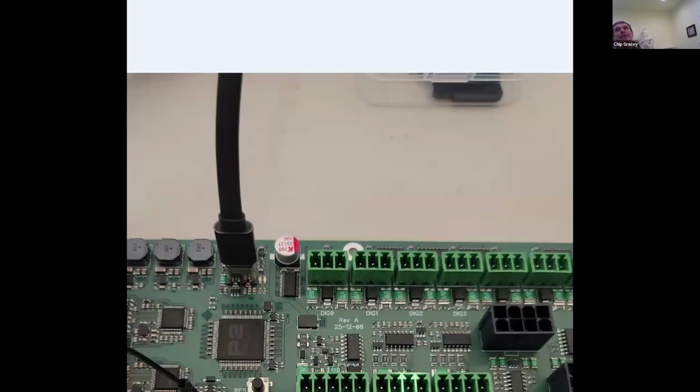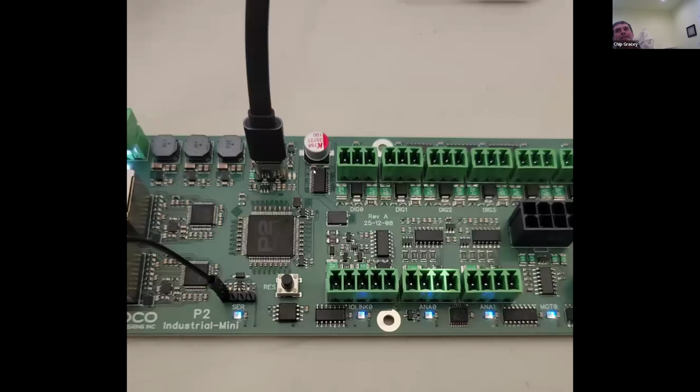Okay, here we are. So you see this here. This is the H bridge, right? There's an H bridge in one of these caps for every set of 8 of these. So this cap is to trap back EMF and things from inductive loads and kind of quench it to the positive 24-volt supply. And all these circuits are going to be fed via this Schottky right here.